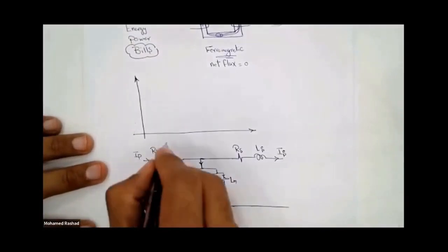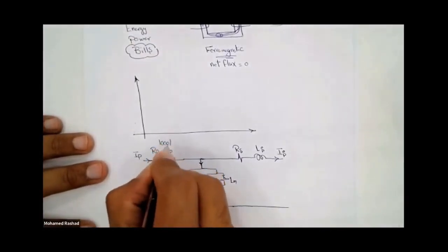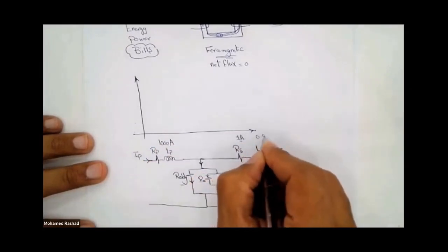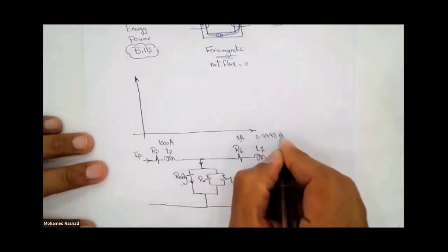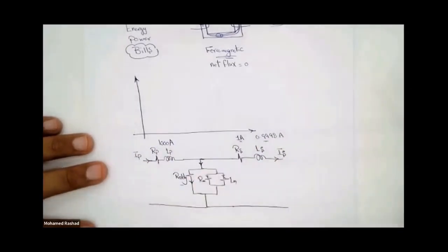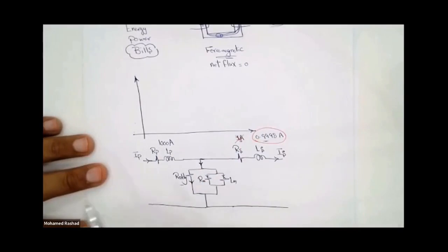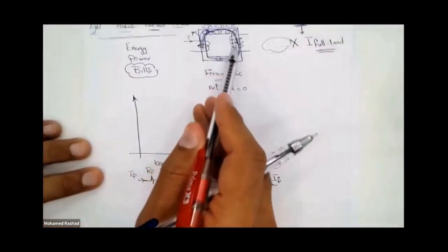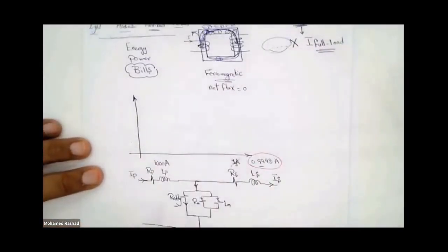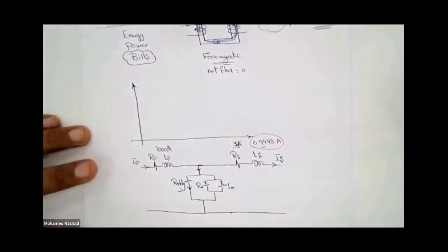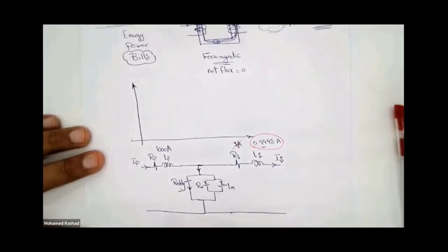This is the reason why the 1000 amperes here do not transform into exactly 1 ampere. Instead, they transform into a slightly different value. Let's assume something like this: if it is 1000 to 1, it doesn't transform into 1, but rather into this value. Why? Because part of your magnetic field goes into magnetizing your core, and part of it generates eddy currents within the core, which do not transfer to the other side. This, of course, causes what is known as ratio error.